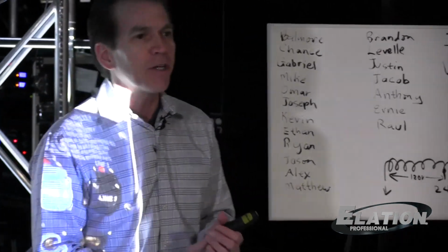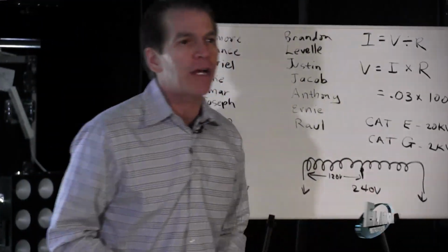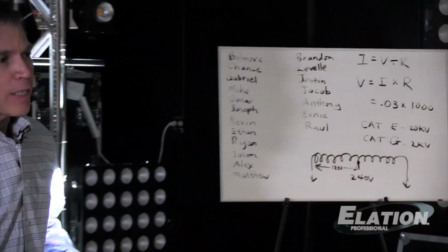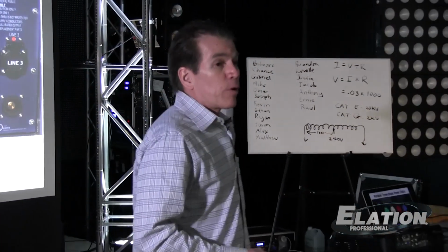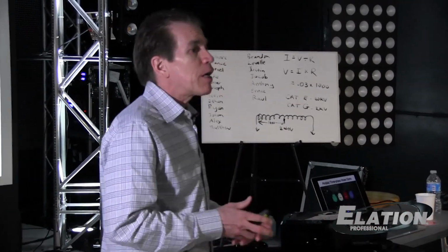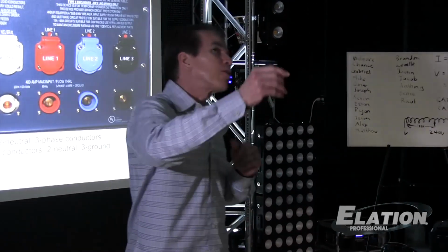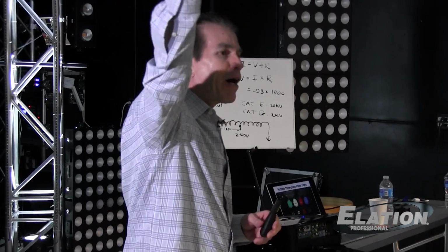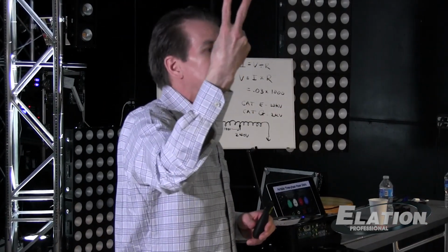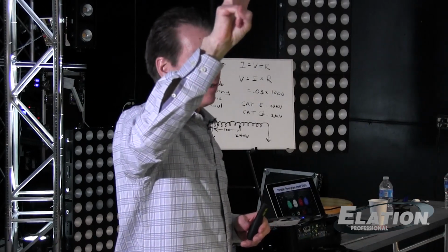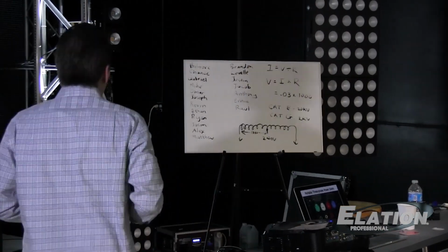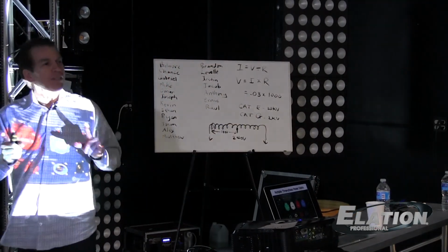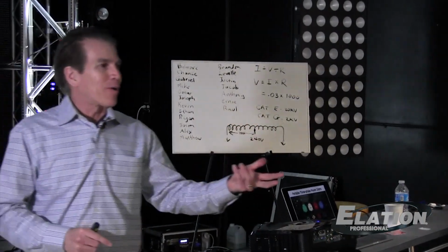So that's what's called a center tap, because the tap is in the center of that winding, and it gives you half the voltage. That's what they do for your house. A lot of times, if you go outside and look at the old style feeder transformer in the alley with the wires coming to your house, there'll be 2 hots and a neutral. You get 3 wires. And the 2 hots are 240 volts phase to phase. That's for your washer and dryer.